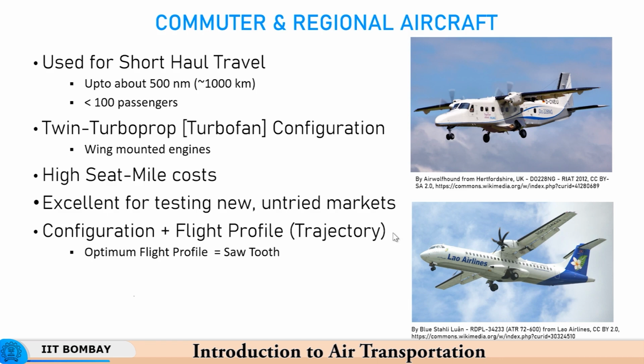In the case of airliners or long range transport aircraft, medium range and long range aircraft, what you will find is an aircraft climbs to a cruising altitude and then spends substantial time cruising at that altitude. In many cases, when we have a long distance cruise, the aircraft actually undergoes 1, 2 or even 3 changes in the cruising altitude. As the fuel is consumed, the aircraft becomes lighter, and as the aircraft becomes lighter, the optimum altitude required to cruise while maintaining the cruise Mach number is higher than what was before, because the aircraft is lighter, you require lower lift to manage the weight. Weight has reduced because of the consumption of fuel, therefore, you require lower lift.